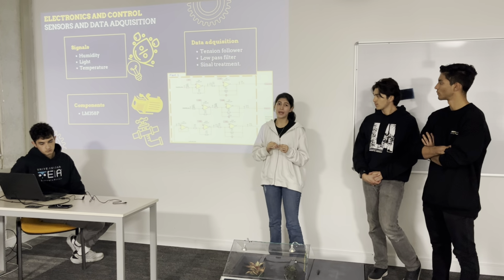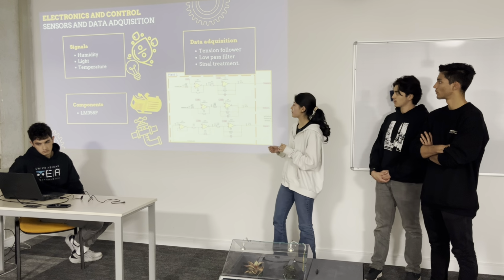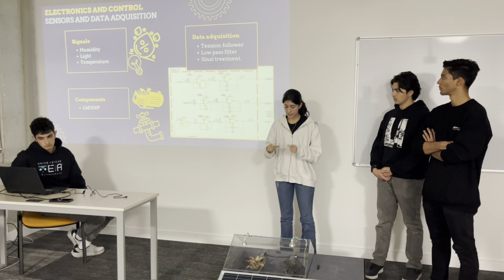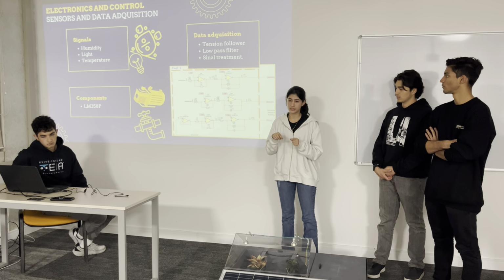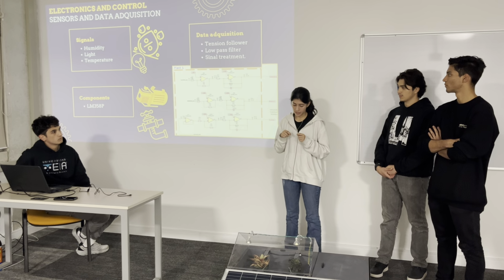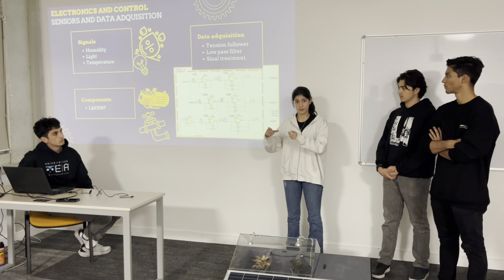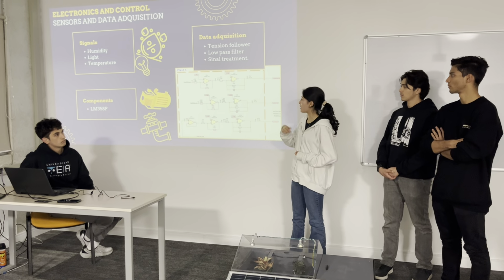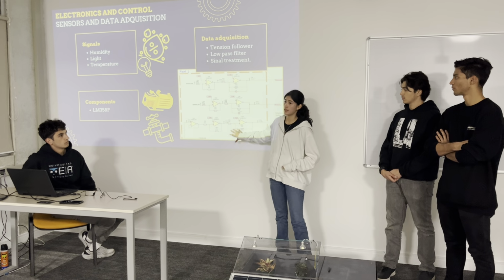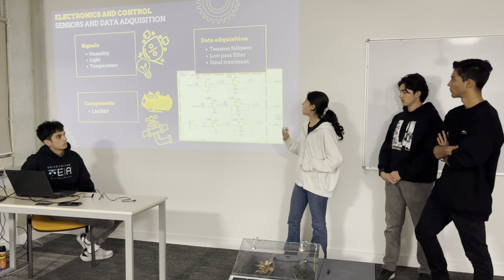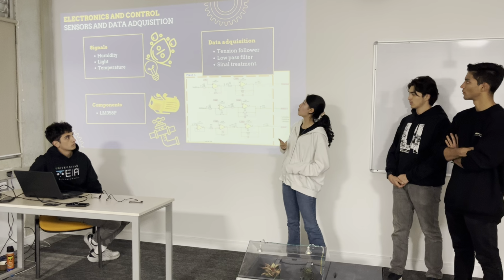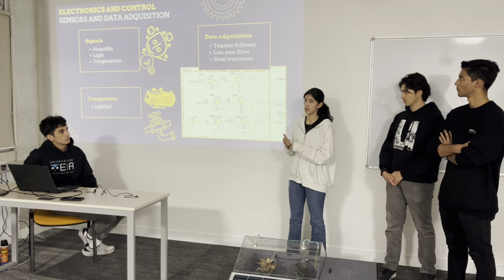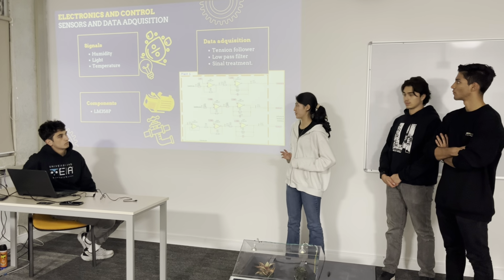We do a signal treatment by having a voltage follower on a little PCB made for each plant, and later we have the signal acquisition with a low pass filter and amplification or de-amplification depending on the sensor.